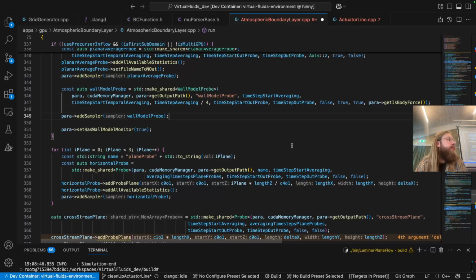How is that actually written? Is that written to the RAM, or how? I mean, are you writing at every time step then actually? And is that a performance problem? Should you be careful how to choose things? No, because it's just going to write like one line. It's the Wallmodel probe. It only takes the average of all the nodes. So it's only maybe 10 statistics, but only 1 point. It's more of a problem if you write out an entire plane.